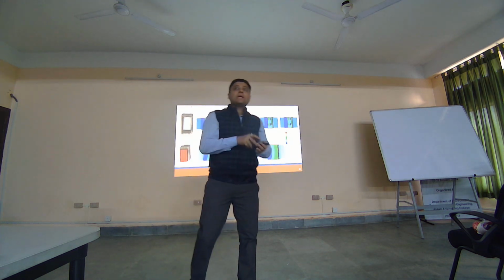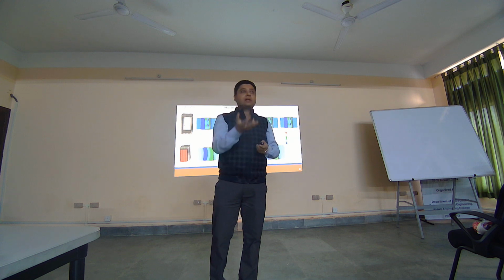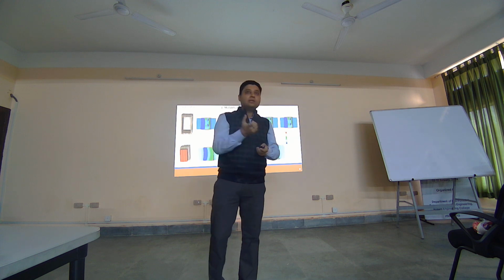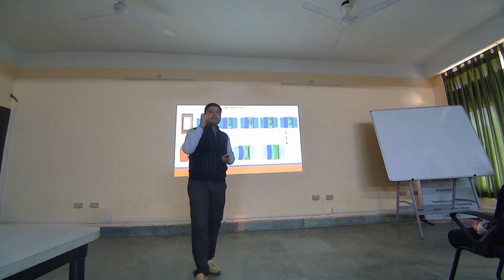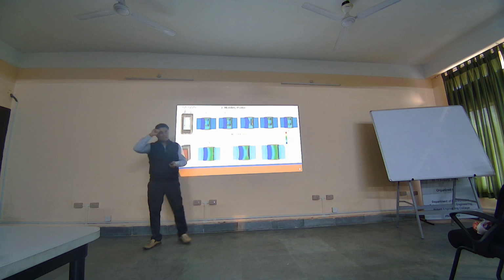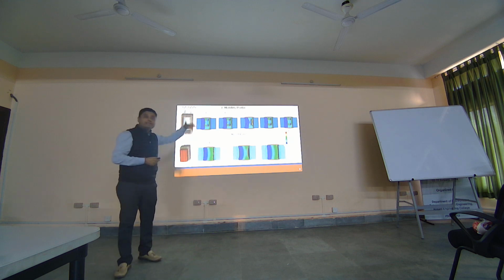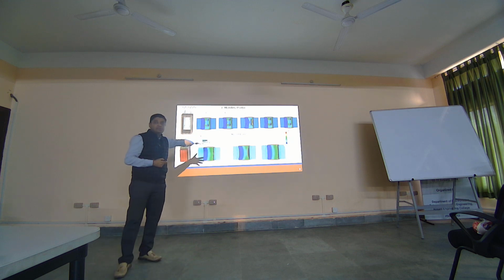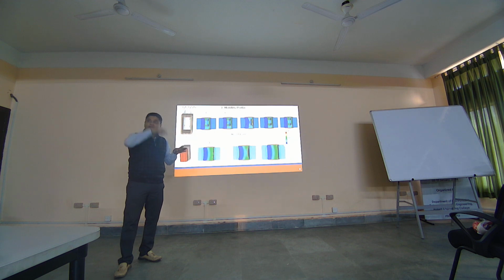Basically, whenever we are talking about defects or traps in semiconductors, most of these traps can also be metallic particles. Now if these metallic particles are located in the bulk of the device, this may be the scenario: they can create this kind of localization within the fin or within the bulk, and then they can steal the electric fields and surface potential from the surface of the device, because that is where we need maximum electric field so that we can have more currents.